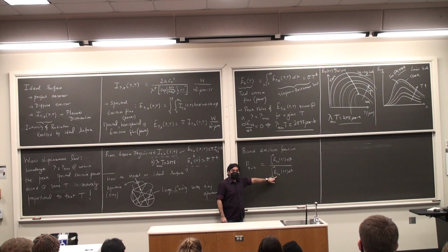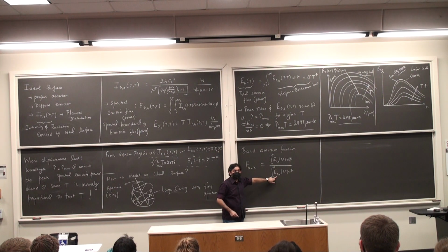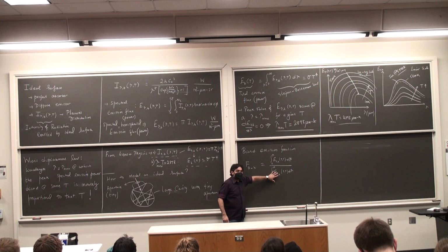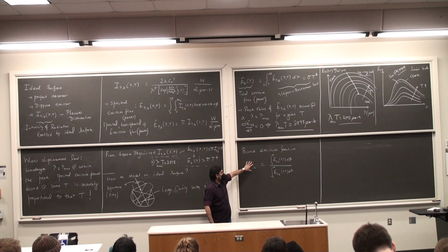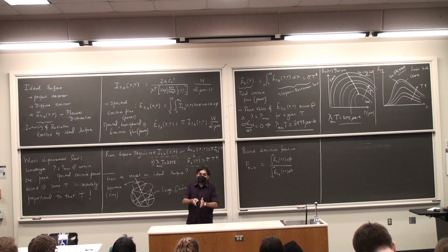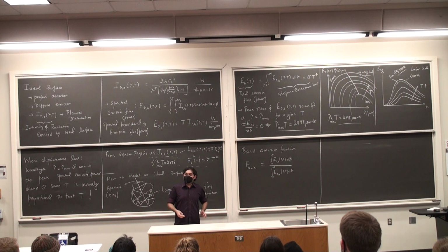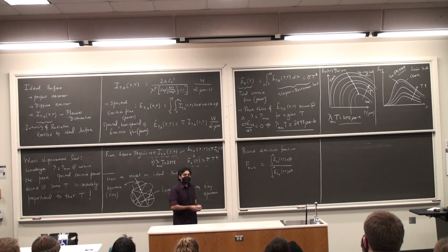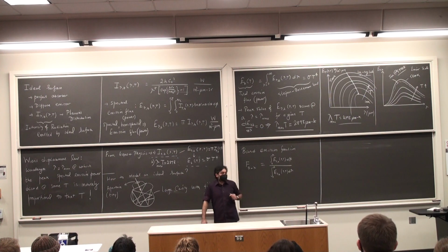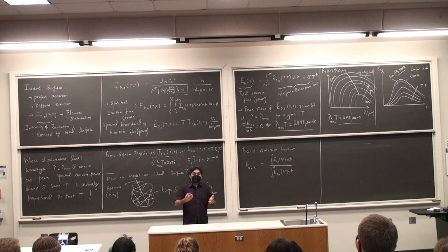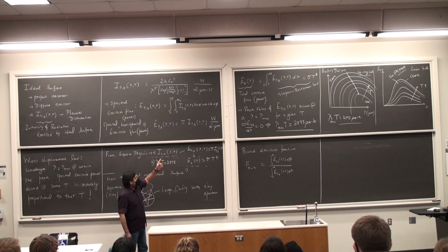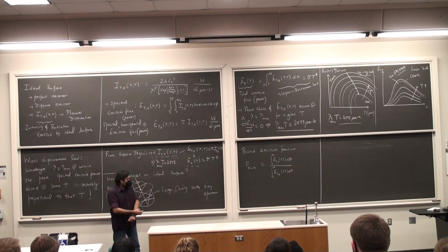What is that equal to? This bottom denominator is right up there somewhere. It is the Stefan-Boltzmann law, sigma T to the power 4, so I know this completely. And if I can calculate these fractions, pre-record them for a given range of wavelengths, then I can directly just use whatever I have tabulated instead of going on calculating these again and again, instead of performing the integration every time I need to do it. It's quite painful, right? 0 to lambda. I can do the integration, it's no big deal, but it's quite messy. Okay, you have to have change of variables and so on.